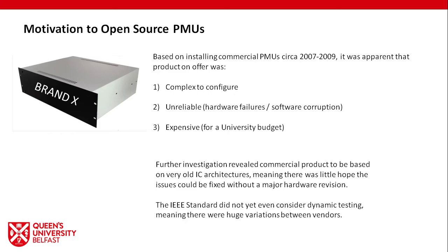The application that I was concerned with really did only require communication of the phase angle of a secure point in the network to the embedded generators, where some logic would determine whether or not the distributed generator was islanded or not.